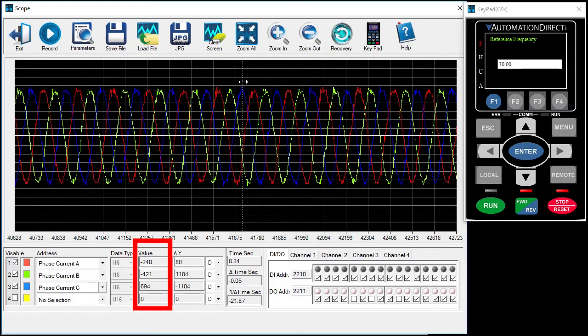The value boxes show the value of whichever cursor you're currently controlling. If I move the dashed cursor, I see these update with the values at the current cursor position. If I move the solid cursor, I see its current values. The delta is the difference between the two cursors relative to the one you're controlling. These display the values in decimal or hex for the next run.